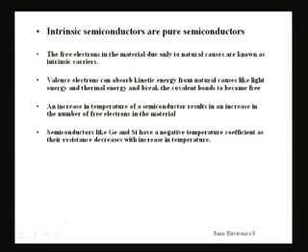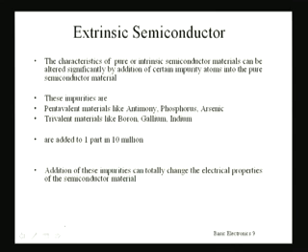So even though they may not be so conducting at a certain temperature, if we increase the temperature, they will be absorbing more kinetic energy and will become more conducting. So semiconductors like germanium and silicon have a negative temperature coefficient, as the resistance will be decreasing with increasing temperature. This is a peculiar phenomenon that is seen in semiconductors, which is just opposite to conductors like metal.